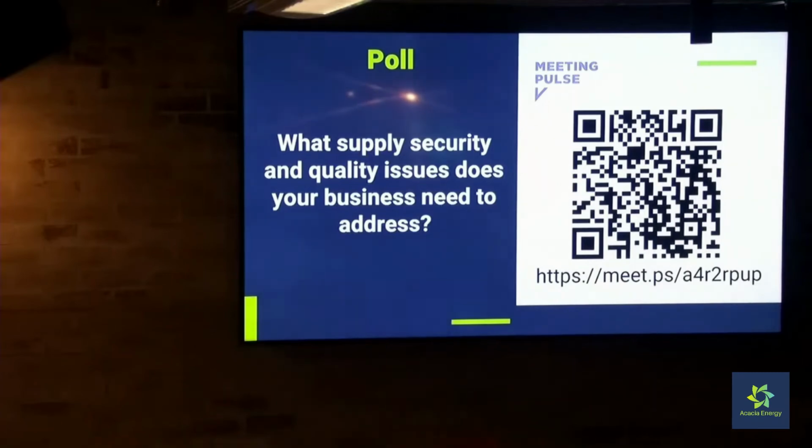So look, with any of your energy security, or electricity security more to the point, there are a myriad of techniques we can use to increase your security, ranging from a few $1,000s up to tens of millions of dollars. If you're unable to quantify the loss you are seeing as a result of these quality issues, it becomes very, very difficult to design a solution that fixes them. One of the most critical things you can do, even before engaging any consultant on a power quality study, is to actually log the losses that you have.